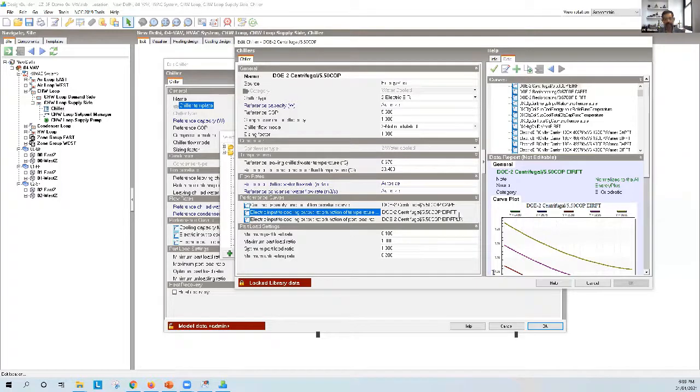That's a big difference between using the detailed HVAC model and using the simple model. In the simple model, there's no part load performance. It just gives you the thermal energy that's required, and you can use a fixed COP and estimate what the electrical energy is. But when you use the detailed model, it does all the part load calculations for the fans, for the cooling tower, for the chillers, pumps, everything.